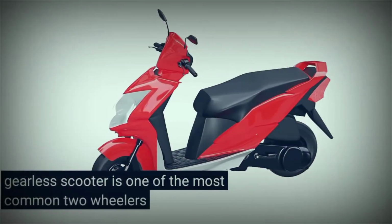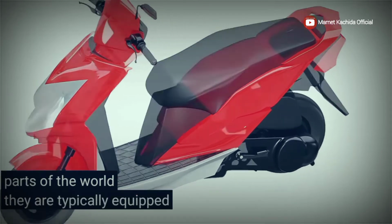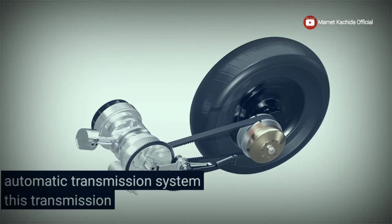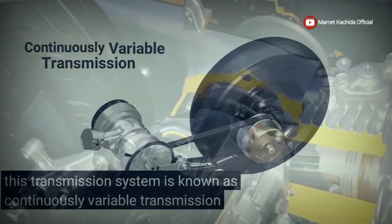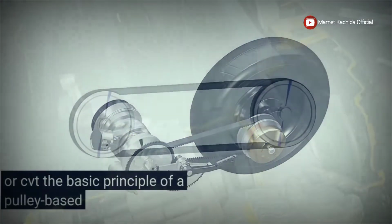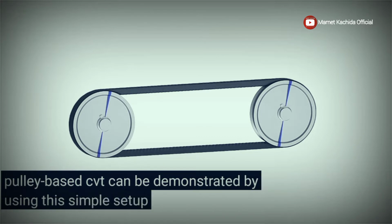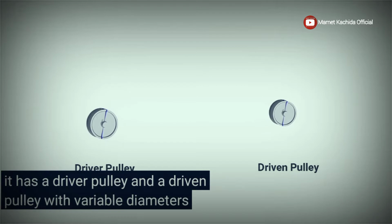Scooters are the most common two-wheelers, popular in many parts of the world. They are typically equipped with an automatic transmission system. This transmission system is known as continuously variable transmission, or CVT. The basic principle of a pulley-based CVT can be demonstrated by using this simple setup. It has a driver pulley and a driven pulley with variable diameters.